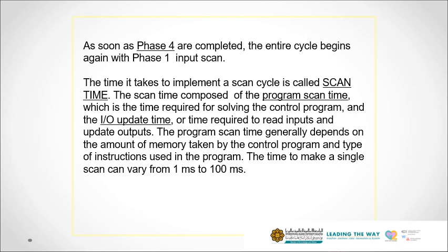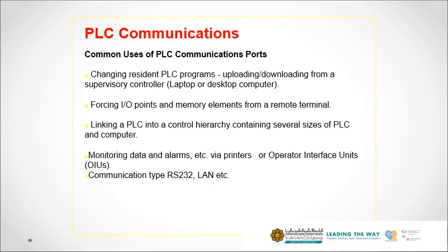Okay, I think that's all. Let me see if I have a few more. Oh yes. The common use of the PLC communication port is basically uploading or downloading the program to the PLC. It is usually done by either USB or Ethernet cable through your laptop or desktop computer.